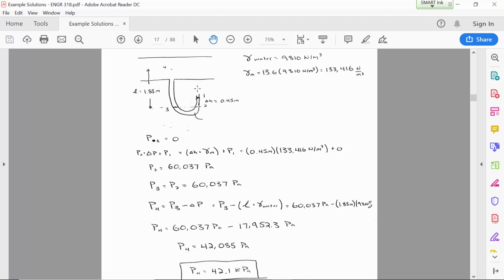So the pressure at the center of the pipe, even though the water is flowing through the pipe, conditions are static inside of the manometer tube. And so we can apply the hydrostatic equation. There's this section that we went through the pipe where it wasn't static conditions, water is flowing through the pipe. But as long as we aren't going side to side, there won't be much of a pressure difference at the center of the pipe because the water is flowing versus if the water was static. So if we go from the opening of this manometer up to the center of the pipe, it's still okay to apply the hydrostatic equation.